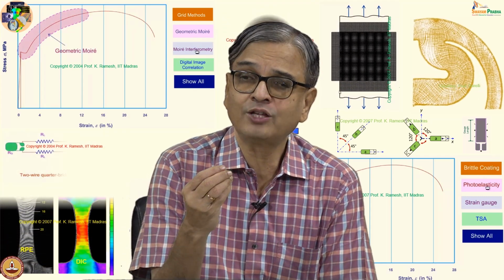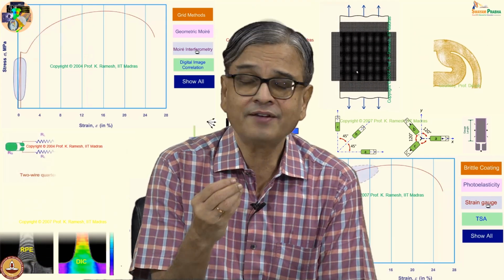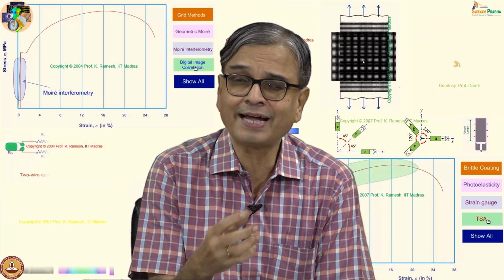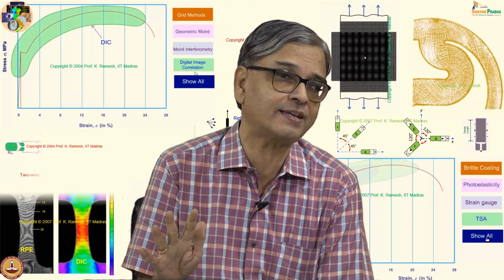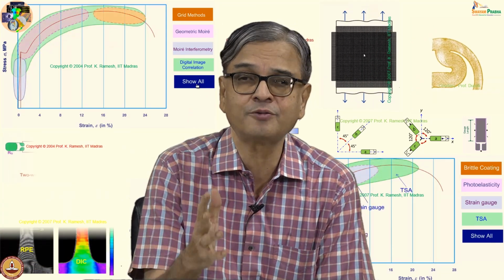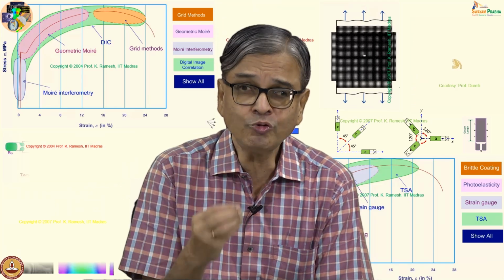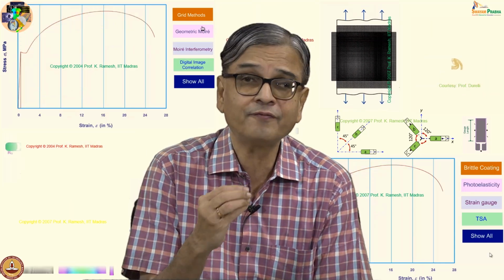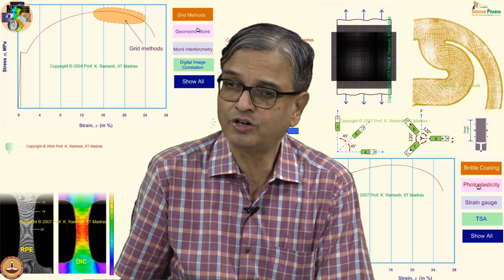When I use it as a transducer, my focus is to measure the weight accurately. So, in order to get the signal properly, I would like to amplify the signal. There is a difference between strain measurement and a transducer application. In a strain measurement scenario, even if the strain is small, my strain gauge should be able to give me the value. In a transducer application, in order to improve the accuracy, I would like to maximize the signal. You will learn from the construction of the strain Wheatstone bridge.